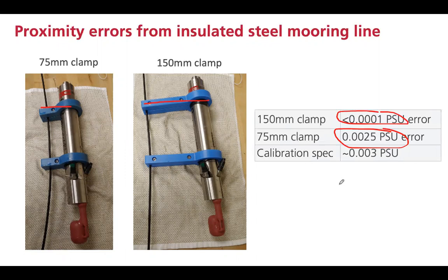And there are times when even larger errors are not necessarily important. If you know Rocky Geyer, he works in estuaries, and of course the conductivity change in an estuary is tremendous in some of them. Rocky, for example, mounts our instruments on a solid mast, and the cell is quite close to an even larger chunk of metal. What he's concerned with mostly is just changes in salinity, and so those are the types of things we're actually going to measure still quite accurately, even with near field disturbance. So whether or not this actually matters depends a lot on your science.